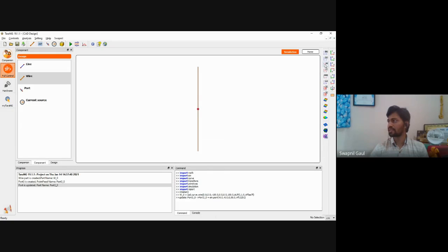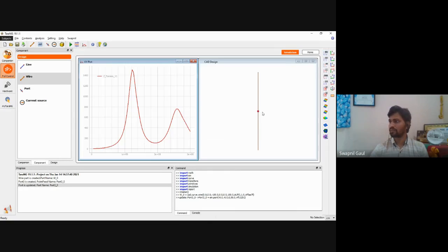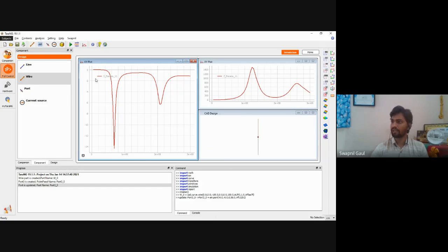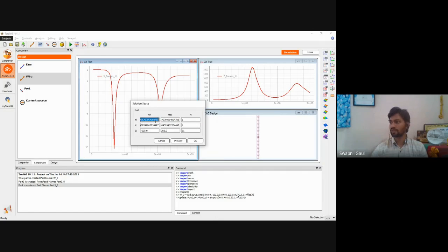Now here we can see these results. The real part of input impedance is again close to 1400. Then the S parameters: the S parameter is again showing this dip around 75 megahertz. So the same things we simulated earlier. We can also see, okay, this 3D near fields.